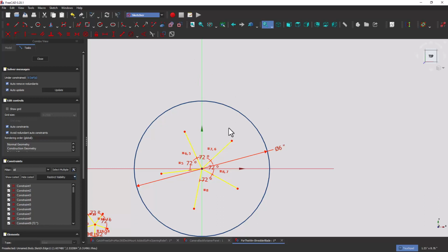Okay, so I'm going to make this a reference line. And the way that you do that is you select it and come up here and make it a construction line. I said the word reference. It should be construction. So construction doesn't get counted in toward any open frameworks, or any open wireframes that you're making here in the sketch mode. I do believe it will lead to an error later on that will delete it at one of the last stages before we go to do a pad on this.